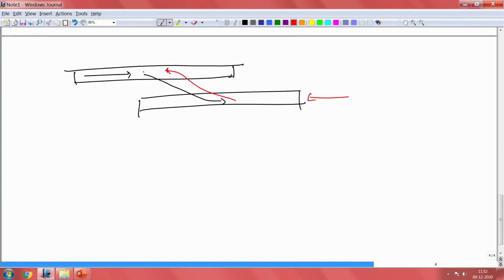Okay. So, by putting waveguides closer to each other, one could couple light between these two. How close? It depends on the refractive index that you have between, let us say, N1 and N2, and let us say this is N1. So, the difference between N1 and N2 gives you what the gap should be. All right.